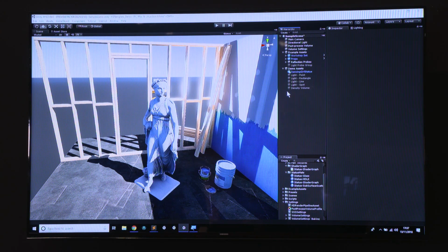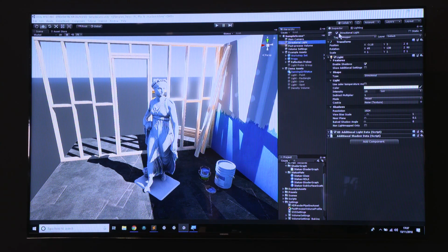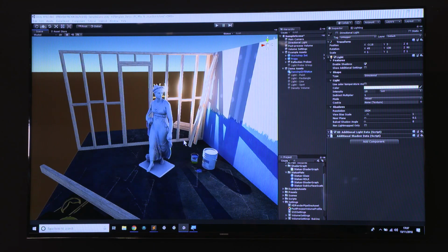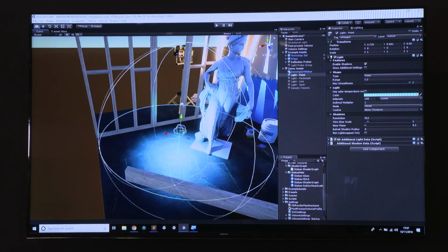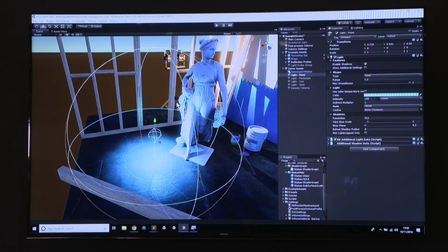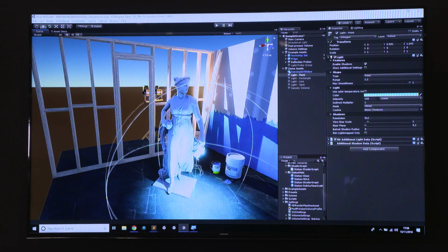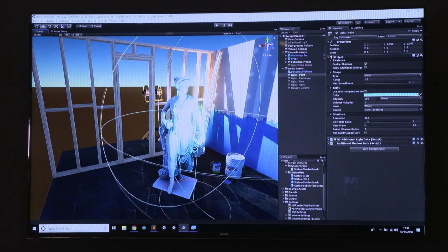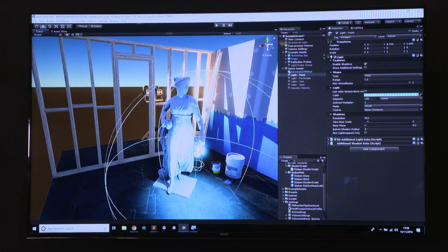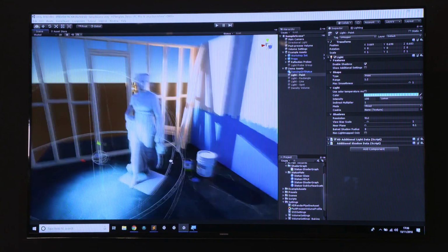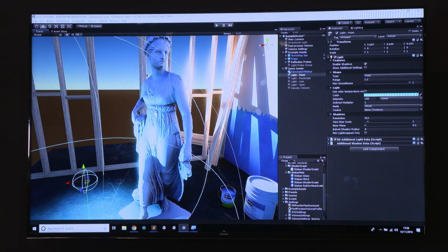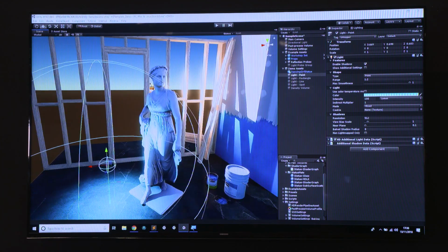One thing I keep talking about is lighting. So if I now turn off the directional light and remove a lot of light from the scene and turn on one of our object lights, what you'll notice is that object lights now have physically based attenuation and falloff. So as I move this light around the scene and around the statue, you'll notice that everything is consistently glowing using those PBR values from that shader. So if I move this light into this position here, we have a nicer physically based falloff using the normal map or the mesh of the statue.